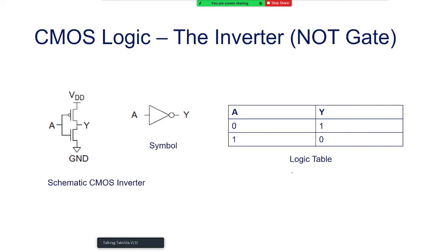So again, this was our concept for the CMOS logic, the very first logic we saw. We understood how the transistors are fabricated, what layers, what masks, what is photolithography, everything, and then we understood their switching action and their operation, how they are used as switches. Once we got that through, we tried to put together a simple circuit. We got PMOS here, and NMOS here, and we said that this circuit acted as an inverter logic. What is the inverter logic, or in other words, the NOT gate?